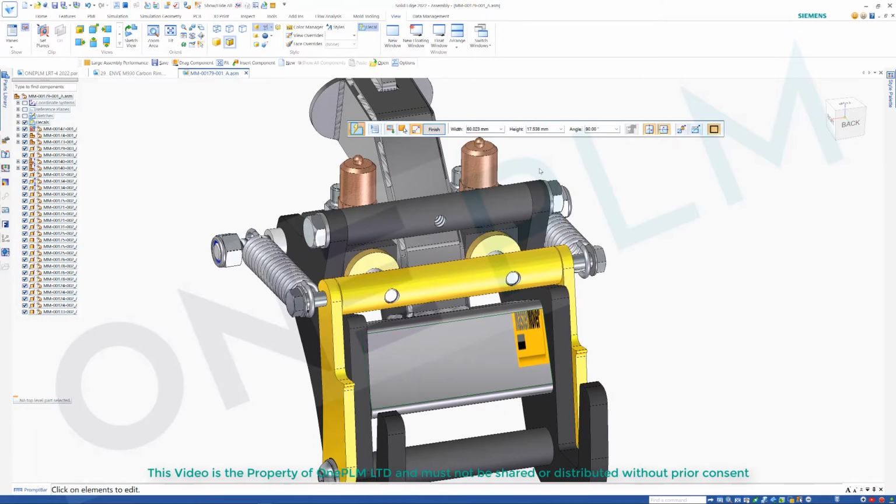So now we've got our aspect ratio. It's kind of the wrong way round, so we need to switch these two values. We need to make sure the aspect ratio option on there is off. I'm going to copy that one. Remember that's 60.23, so I'm going to paste that into there and go 60.023 in that.